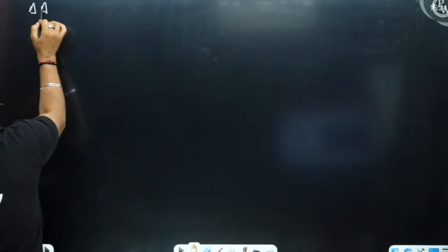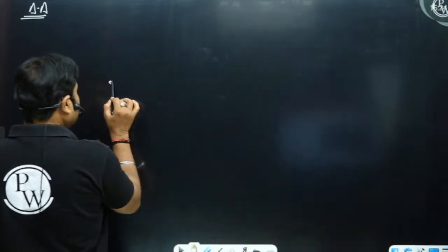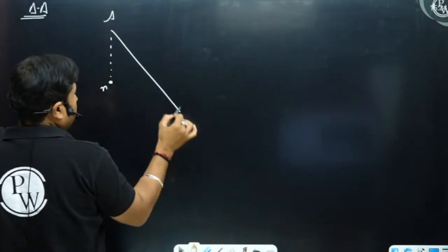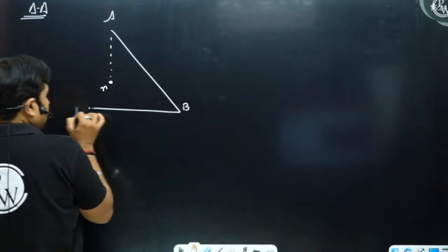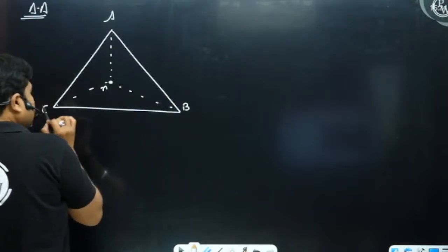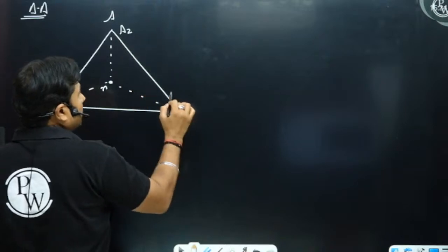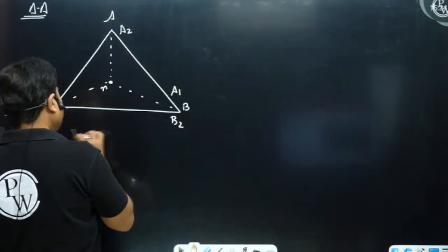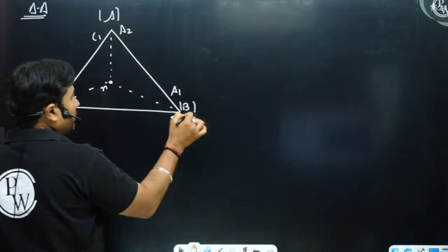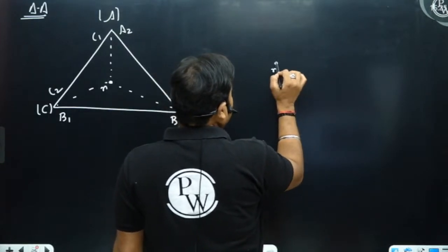a delta delta connection, we can take a reference node and then A, B and C phase. Make a delta, consider a neutral point, take HV at 12 o'clock position, and then make a delta: A2 A1, B2 B1 and C2 C1. A phase is brought out from A2, B phase is brought out from B2 and C phase is brought out from C2. Same neutral will again be drawn here.